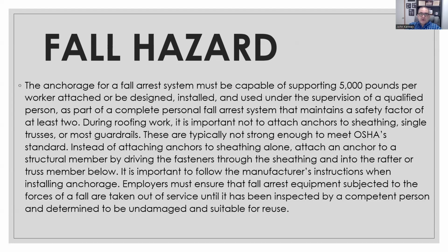As an employer, you must ensure that fall arrest equipment subjected to the forces of a fall is taken out of service until it has been inspected by a competent person and determined to be undamaged and suitable for reuse. You've got to be real careful with this. Sometimes it is not worth putting anything back in service. You get new equipment after there's a problem. So again, if you are planning on putting this type of program in place, make sure you're dealing with a certified safety professional who can do this for you.